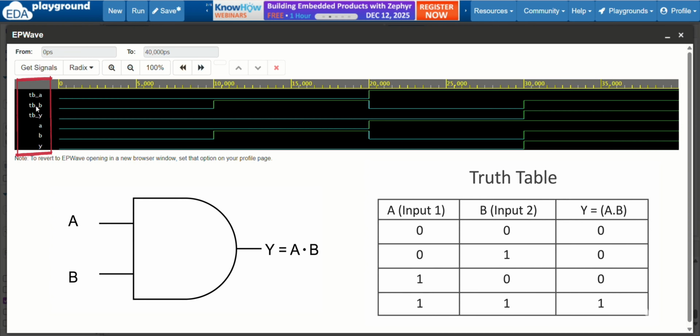Now why do they look exactly the same? The port mapping. In the test bench we have seen the port map we have written, where a => tb_a. We have seen that, no? So we are virtually connecting that wire to that pin, because they are physically connected. So whatever voltage is on the test bench wire tb_a must also be on the gate pin, that is a.